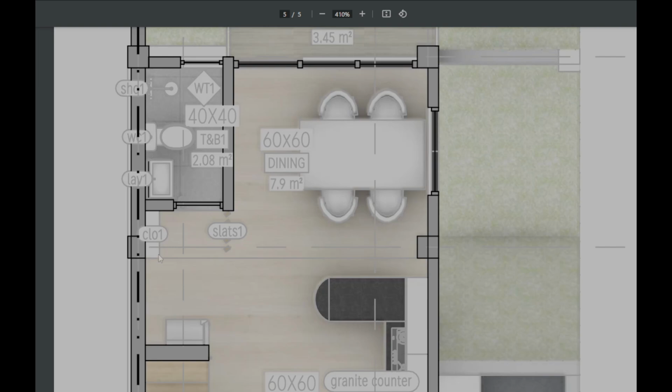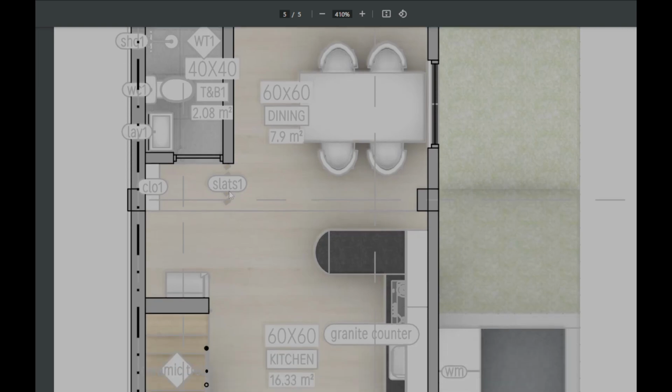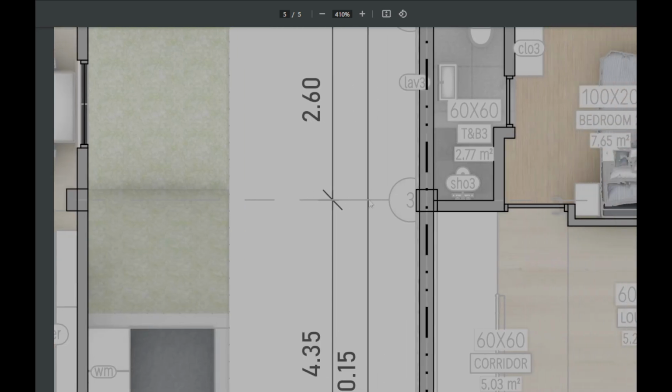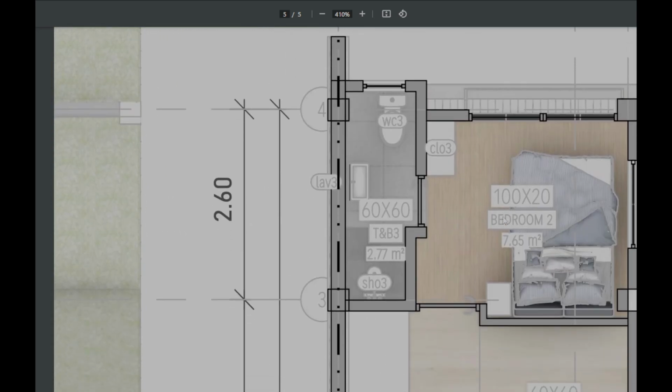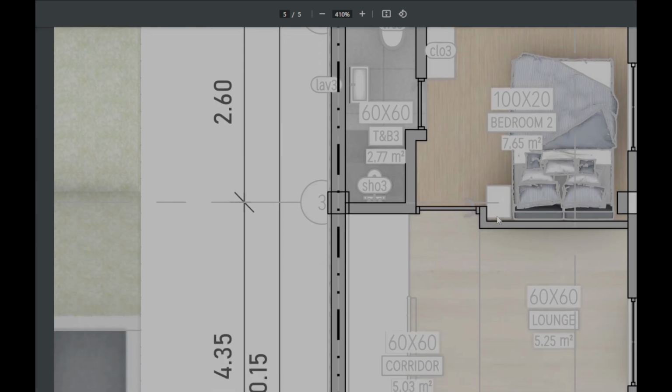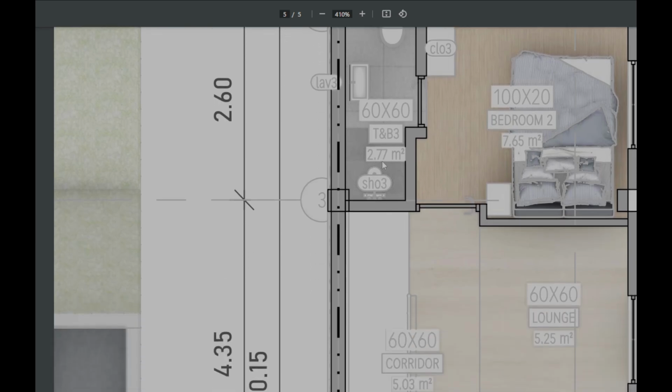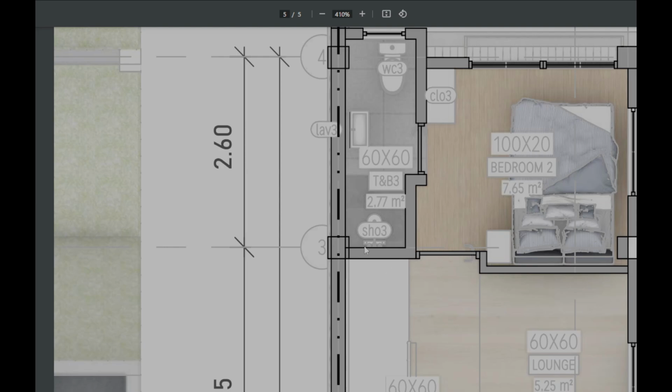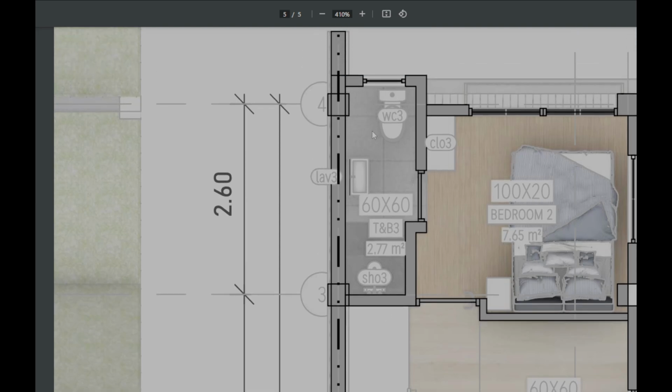So until we go to the interiors, until the closets, until the slats, lahat yun kino-compute rin namin kung magkano, ilan ang pako na pupunta doon, ilang plywood yun. That's why we do not always rely on the per square meter basis. Yung, eto, 2.77 square meters times 28,000. Hindi ganon. We need to know what's the material because magkakaiba ang presyo.